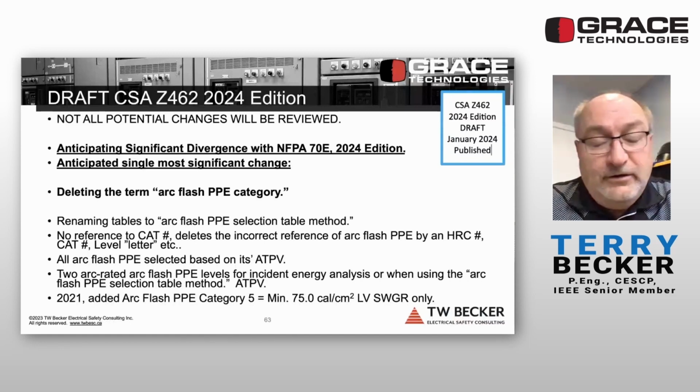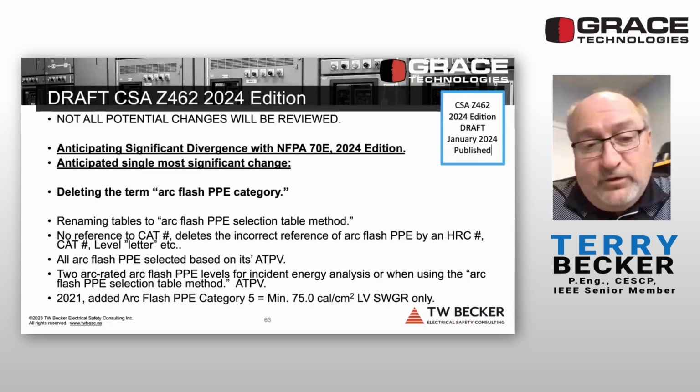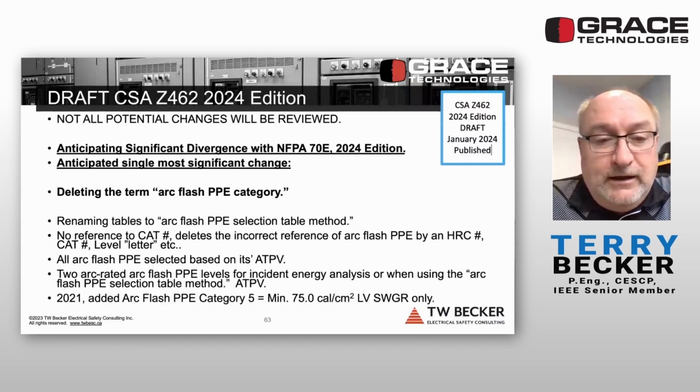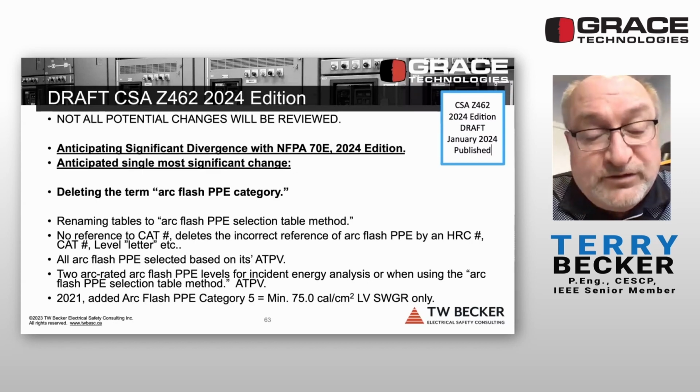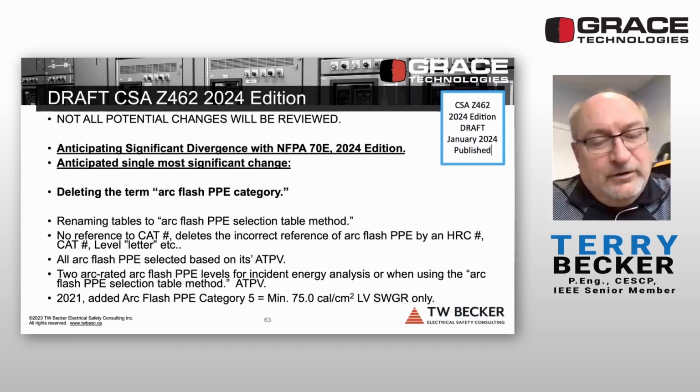Oberon Company, the leader and innovator in arc flash PPE, has always had those higher ATPV arc flash suits, but again, misinformation about what I call the 40 cal myth, because 40 calories was miscommunicated as implying that arc blast pressure would be thousands of pounds per square foot, which was false. So if you haven't heard that yet, you're hearing it again. Well, you're hearing it from me that 40 cals is not a stop point for energized electrical work.